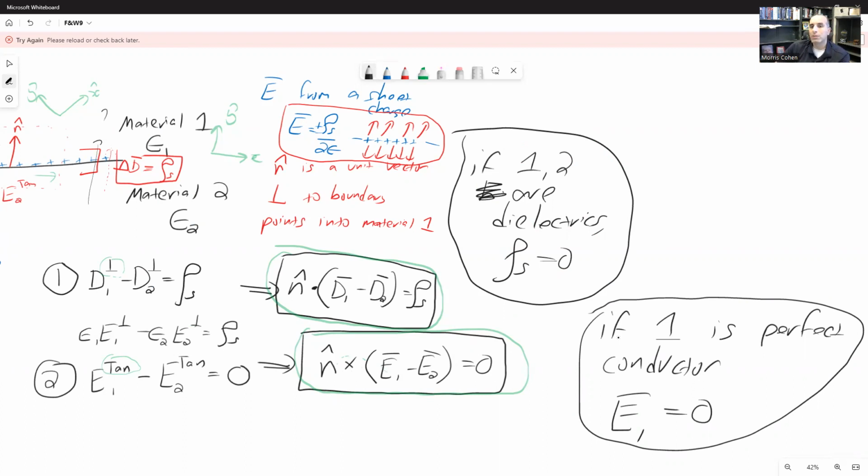But a lot of realistic materials actually have both dielectric and some conductivity to them. So you can't immediately dismiss that. But if we go back to Poisson's equation from the last video, if I have a boundary between two materials inside of the space that I'm solving for, I need an extra set of equations in order to relate charges to voltages. And boundary conditions is exactly what's going to give that to us.